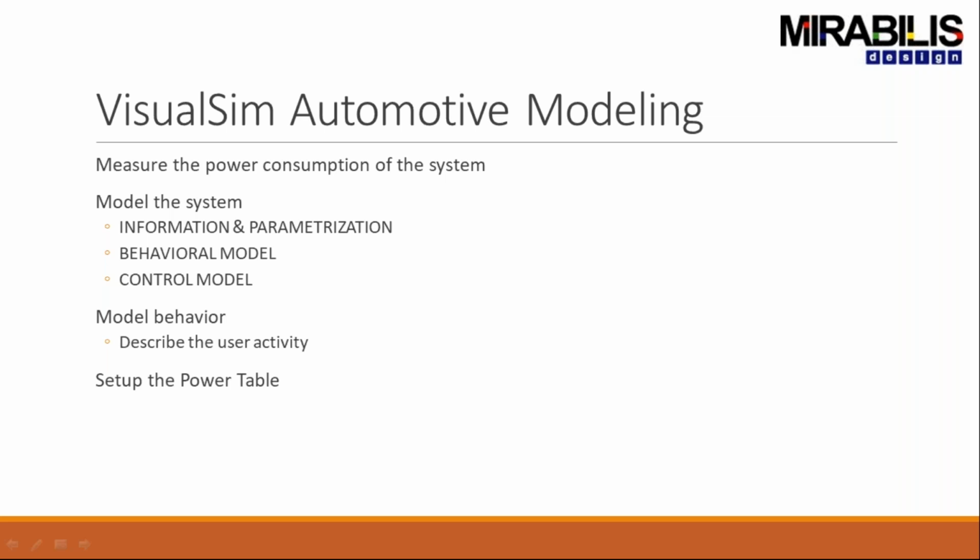So architects very often want to reduce the power usage so that the recharge time cycle can be reduced. In VisualSim, we provide the user with power modeling tools embedded in the library, and you can model the system in a behavioral format where we can map the task to hardware resources. VisualSim helps the user calculate various metrics like resource utilization, response time, and buffer usage.